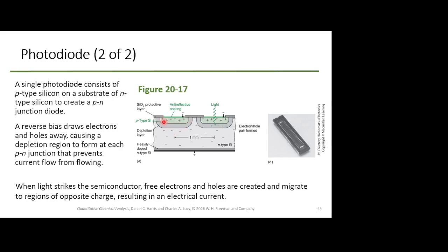That's a little cutout. There's going to be an anti-reflective coating on this so that it does not reflect the light back out and then cause it to trigger itself again. The light will then come in. Note if it comes in at the wrong angles, it's very likely to get blocked and not give you the proper detection. So it's only a very set width of angles that will work with this.